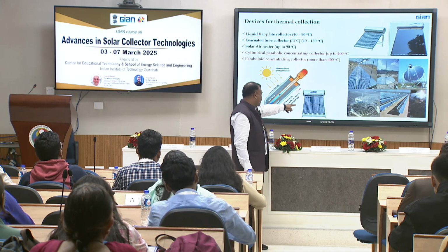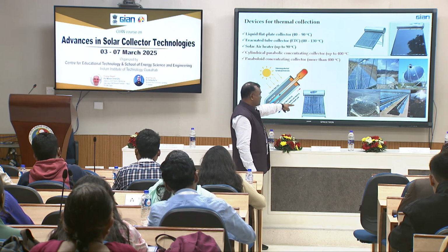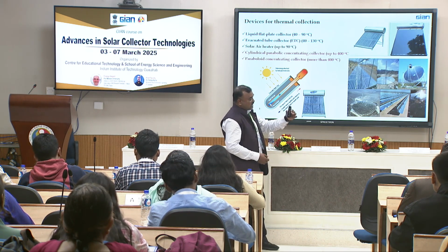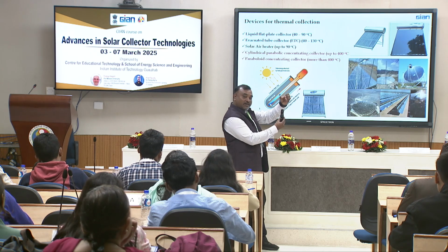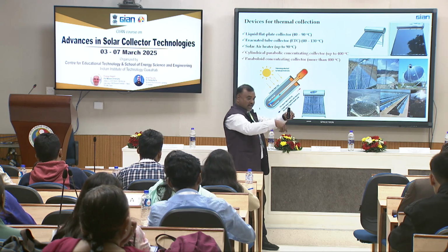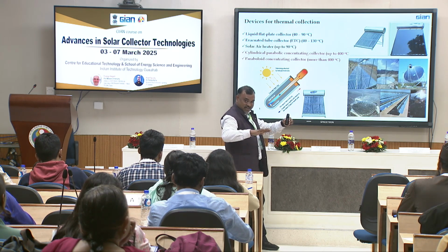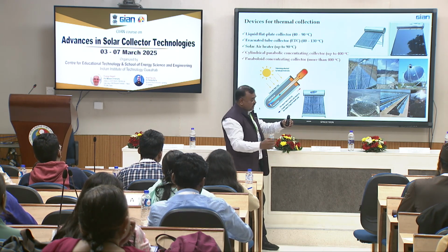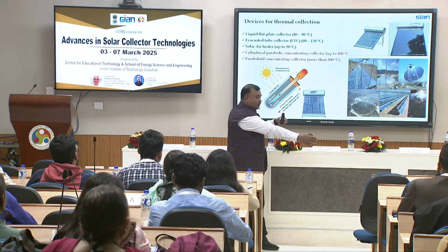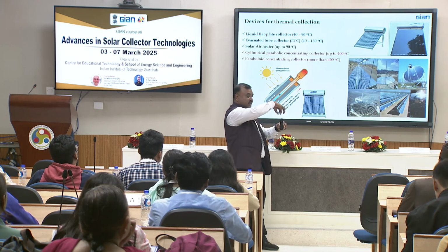So, what you can see at the bottom is a central power receiver system. So, you have a pole here, at the top you will have the absorber, and along the periphery you will have all the heliostats. So, it is a glass kind. Solar radiation falls, it reflects to the receiver. So, from all sides it comes and is received at the receiver at the top.